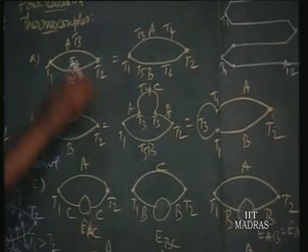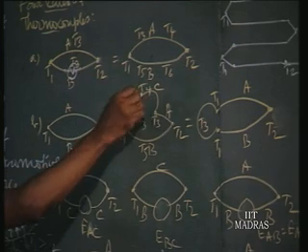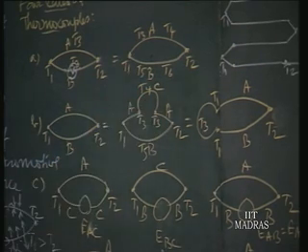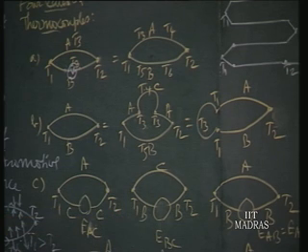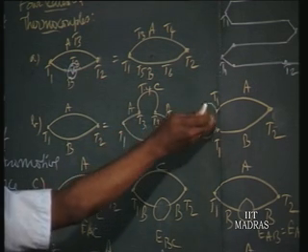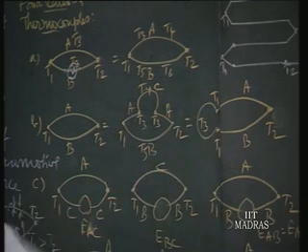Also we find that the law of intermediate temperature also holds good. The third material can be exposed to any temperature later, like this say T4, it will not affect the EMF. And here we find the third material is connected at one of the 2 junctions. Here at the T1 junction, the new material is connected.